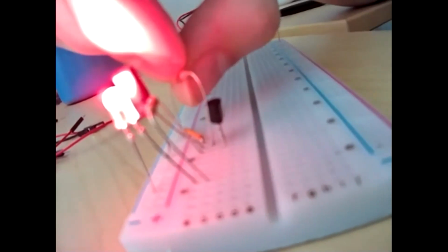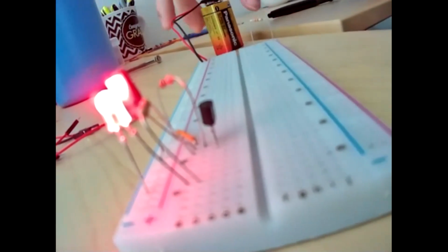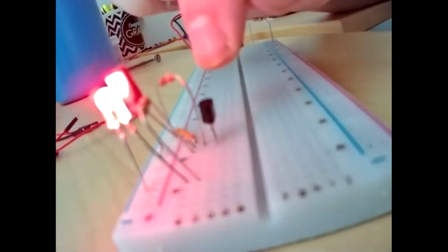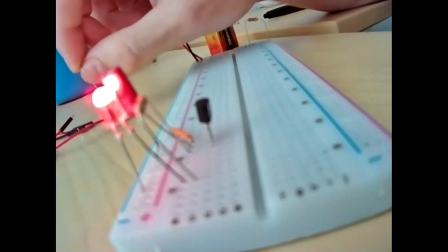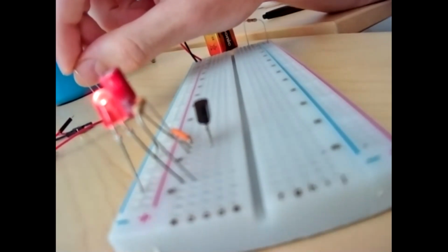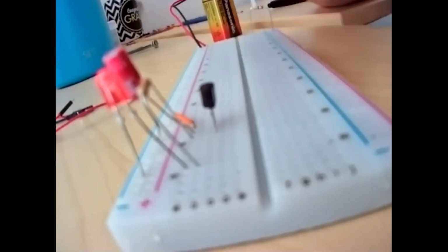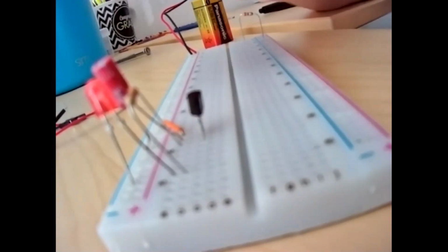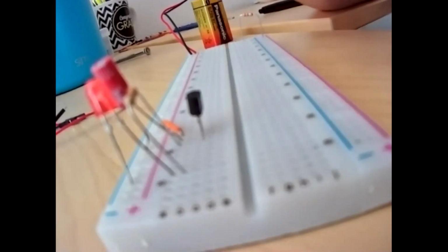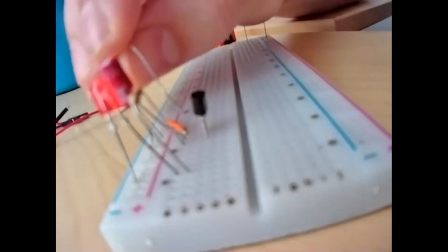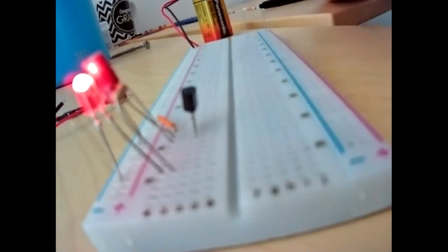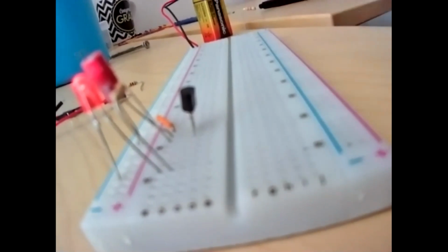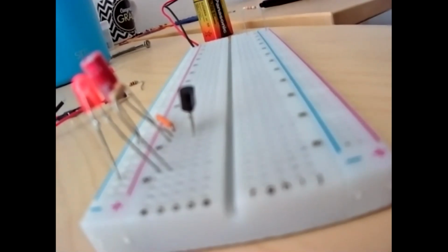So once I remove this, the battery is gonna be disconnected from the base. So the capacitor is gonna discharge. And so I'm gonna pull this out, and you'll see the LED slowly fades away, right? It's kind of hard to see, but it's still on because the capacitor is still barely discharging, because it sort of gets to zero as time goes to infinity. So if I plug this back in, it's gonna light up, and then if I remove it, it slowly discharges away. So yeah, those are the 3 circuits I wanted to talk about.